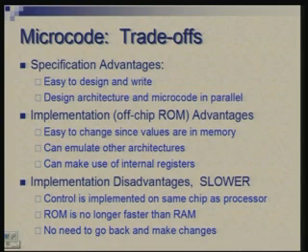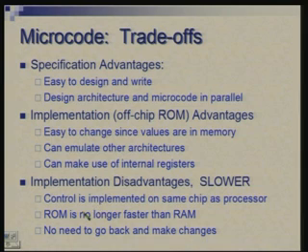You try to simulate the effect of another set of instructions, and the microprogram would have access to all the internal registers, temporary registers. For example, in our design we have registers A and B. A person working at assembly level will not know that there are registers A and B, but one who is working at microprogram level could access those registers if it is required for implementing something. But the penalty of all that is that this approach makes it slower, because memories would tend to be much slower than the PLAs, for example, which is the other alternative.